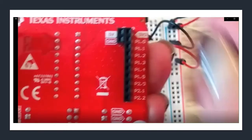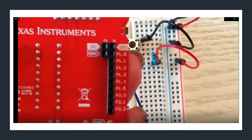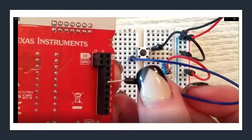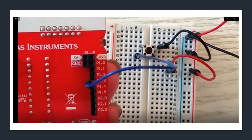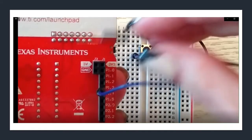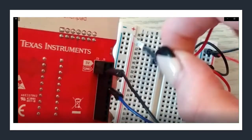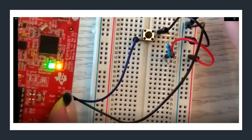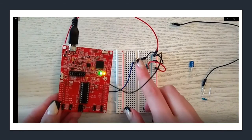So when I turn over the board, you can see everything is labeled underneath. That's where we'll be plugging our wires in. So first I'm going to plug in my push button to pin 1.3 because that's the same pin that we used to program the push button on the board. So we're going to use the same one so we don't complicate things. I'm going to plug in my ground wire, and I will plug in my power wire. All right. So now this is my setup for plugging in one push button, and now we'll go ahead and test this and see if it works.